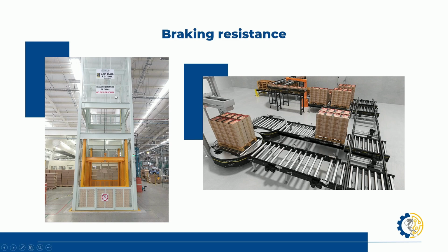Okay, so if I wish to stop my crane, for example, let's suppose that there's a sensor here already, and when it detects this sensor while going down, how about if it stops braking little by little so that it has some deceleration time? And if we calculate so that it starts decelerating little by little, all the way until it gets to its limit, its set point.